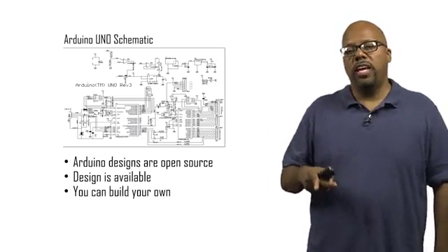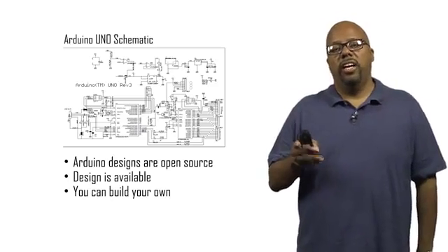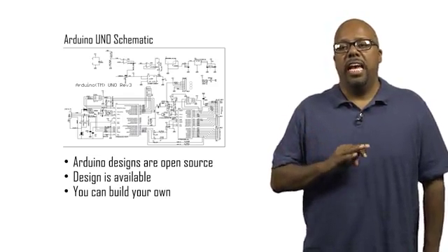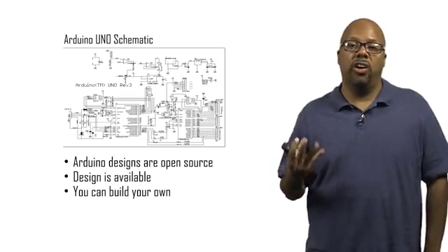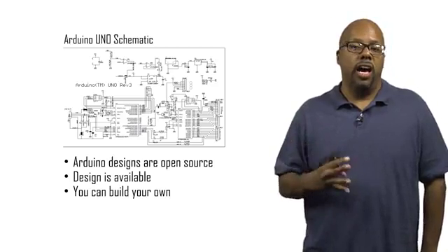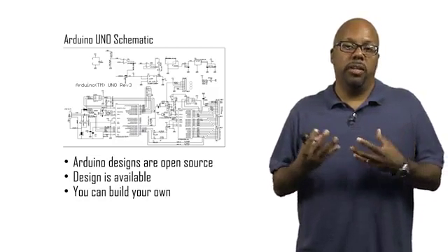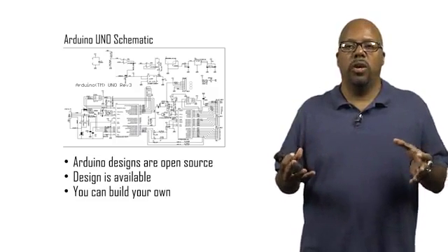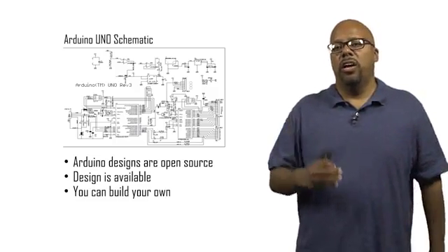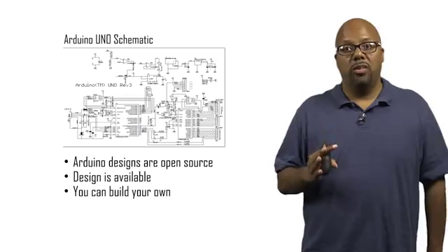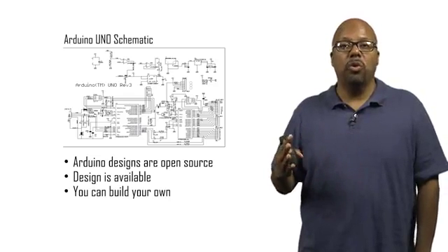Notice one thing too, that the layout you see drawn on the schematic has nothing to do with how they are laid out on the actual board. When they lay them out on the physical board, placing the parts is done in such a way to make it compact. On the screen, when you see a schematic, you're not necessarily worried about compactness, you want it to be more readable, right?